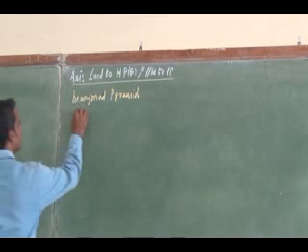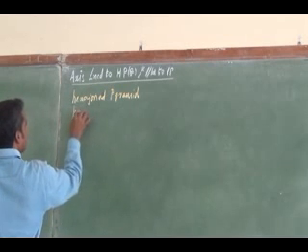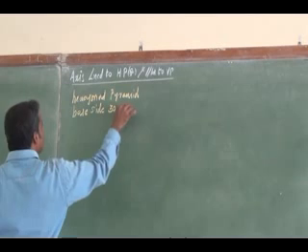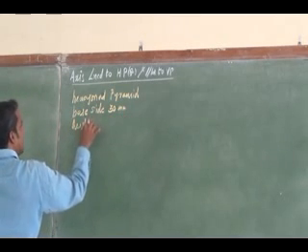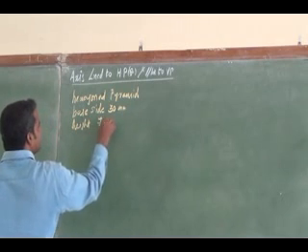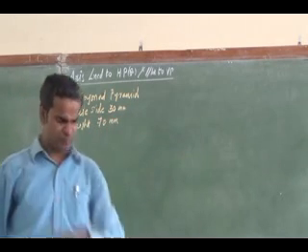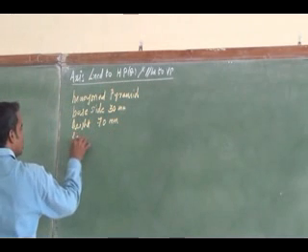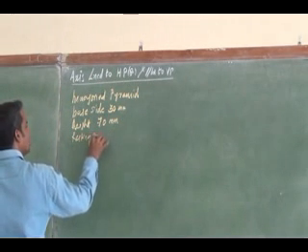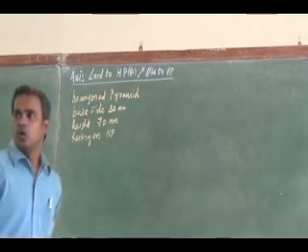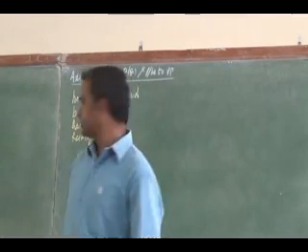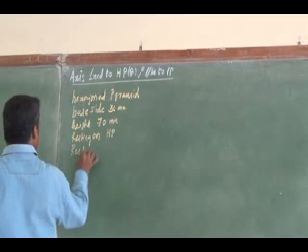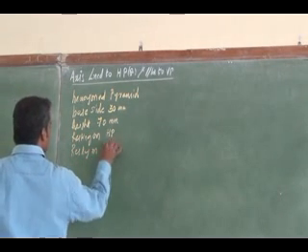It is a hexagonal pyramid of base side 30 mm and axis height 70 mm, resting on HP with one of its base edges.